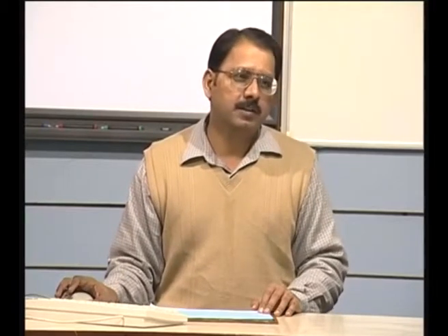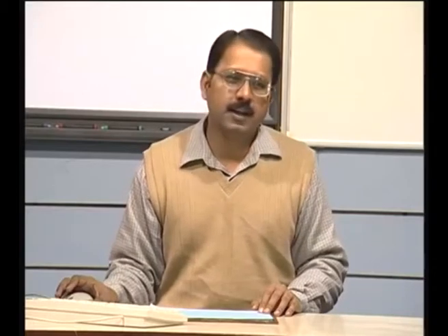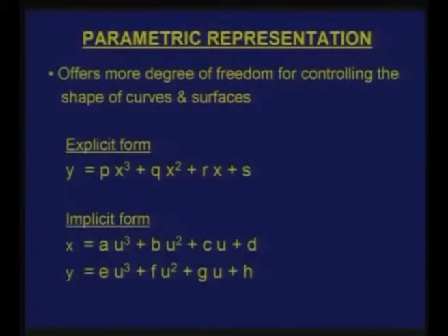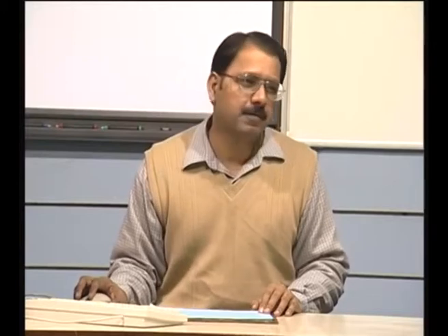Another major advantage of parametric representation is that it offers more degrees of freedom for controlling the shape of curves and surfaces. Like I have given two curves here, which are y as a function of x, and x and y as functions of a parameter. So, what you see is two different types of representation, one which you call explicit, and the second, sorry, this is not implicit, what is shown here is a parametric form. It is wrongly written as implicit. So, this is a parametric form.